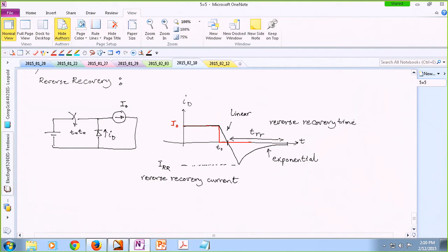So these are all given for a certain test condition under which the manufacturer performed the tests, and they are an indication of how much energy you would lose in your diode, and how long it would take your diode to actually turn off. You can associate several disadvantages to this reverse recovery phenomenon. One of them is power losses. We have electric charge going somewhere it's not supposed to go. The voltage of the diode is ramping up, so when you multiply the current by the voltage, you get non-zero curves. So you may lose some power because of this.